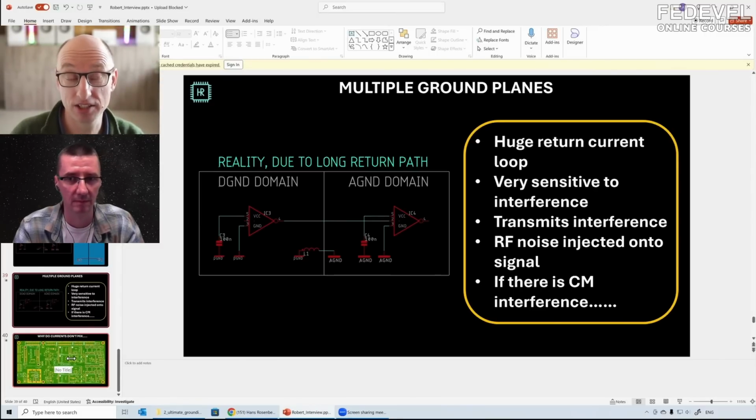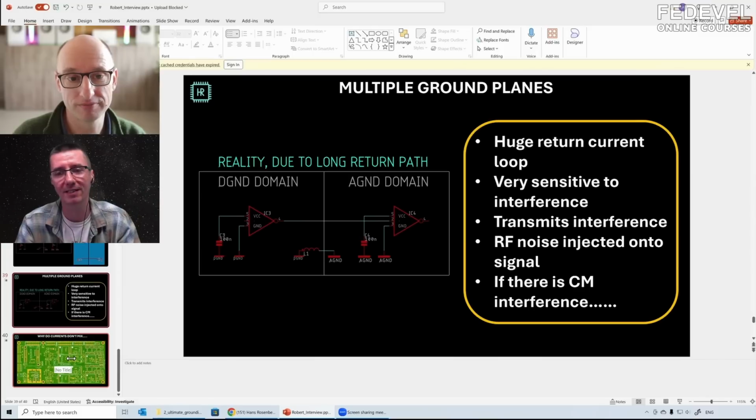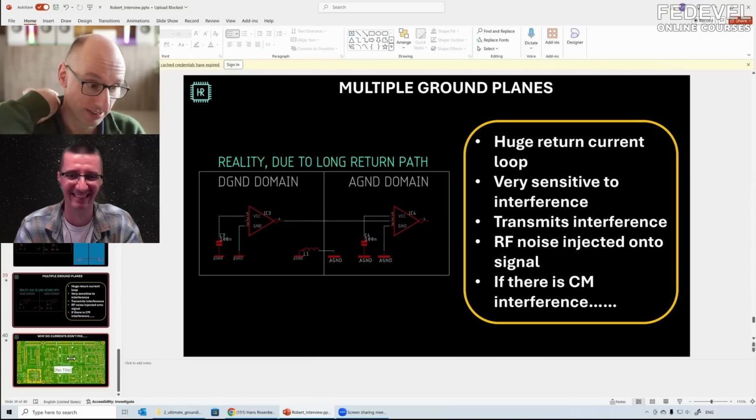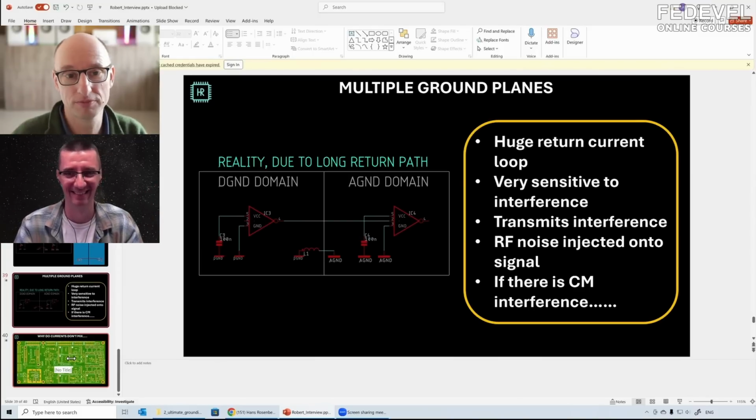Yeah, exactly. That also keeps the loops as small as possible. If you place it far away, it would not work. Yeah, because even the DC resistance would kill the application in this case, even if you use multiple layers and planes to conduct power.